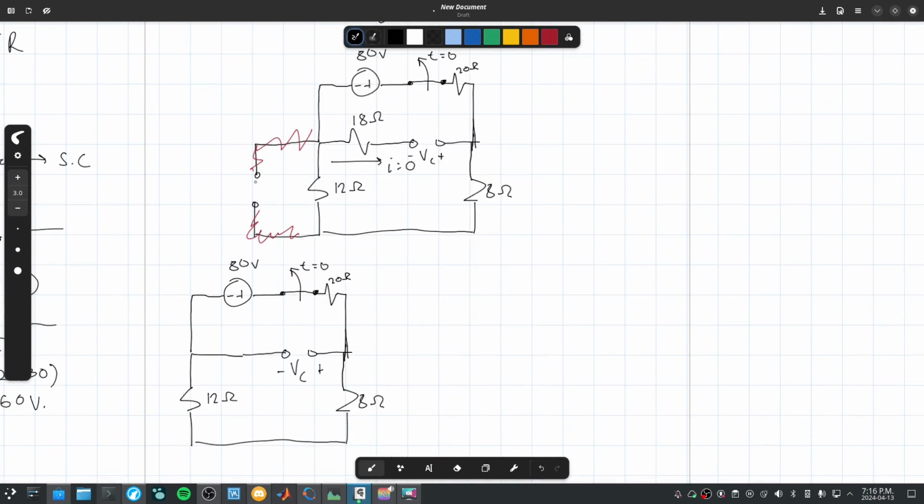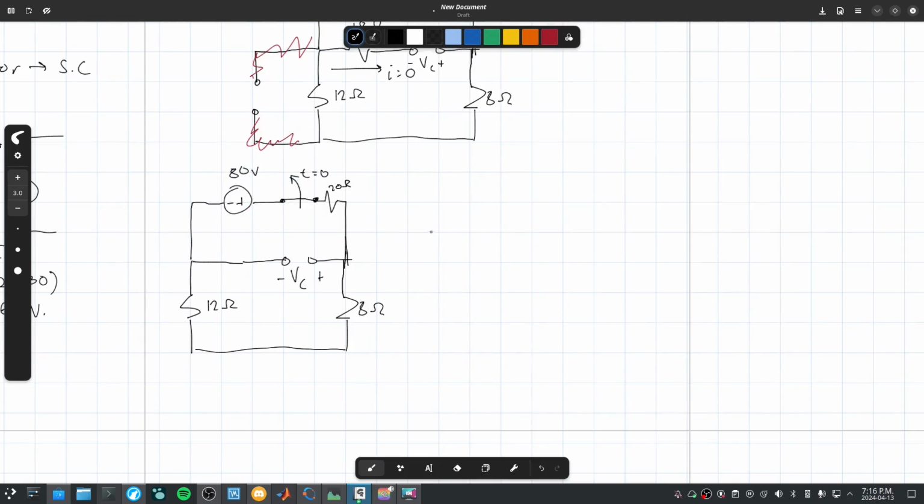I'm confused why you removed the resistor. Okay, so if I have a circuit here with a resistor in here, if there is no current running through it, then the voltage here is equal to the voltage over here. So there's absolutely no voltage drop, so it might as well not exist.